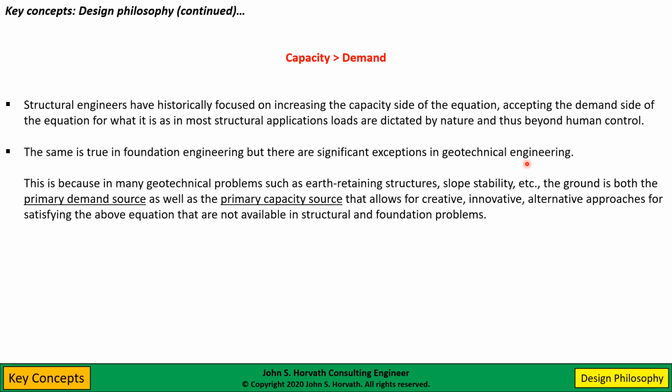And that can be very challenging, especially, I think, for LRFD. LRFD, as is well known, was really developed with structural engineering primarily. It becomes more challenging to apply it to geotechnical engineering because we have the same system, the ground, that is influencing both sides of the equation. But this actually works to our benefit for what I'm talking about in this presentation, because it allows for creative, innovative, alternative approaches for satisfying this equation. It basically allows us to do things we can't do in structural and foundation problems, where we have to live with the demand that nature provides.